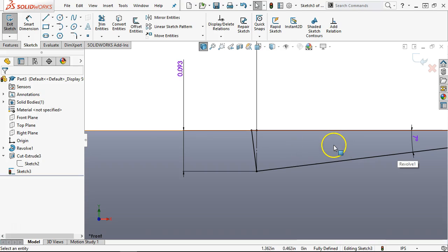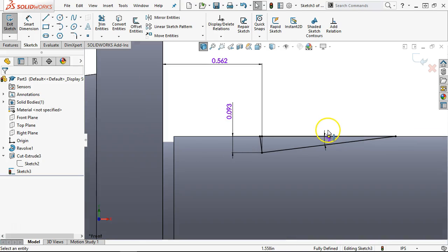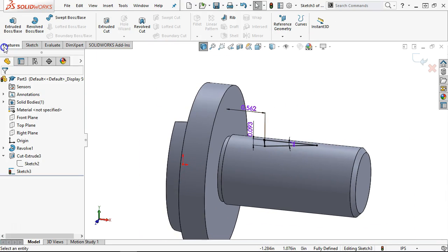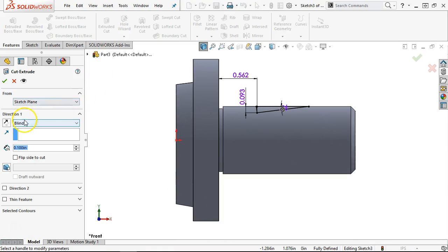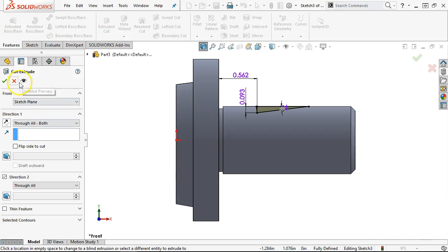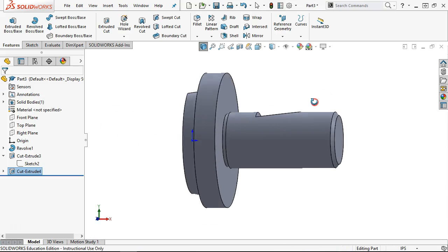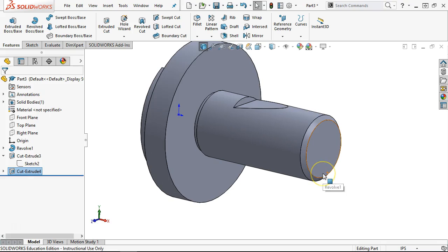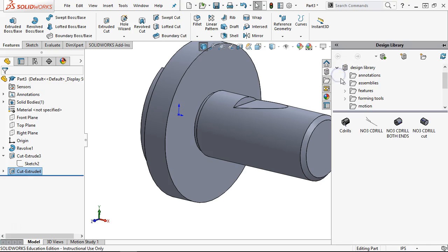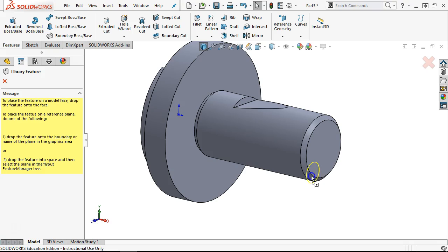Otherwise, this becomes a little bit more of an angle cutter and a little more complicated to make that edge vertical. And if it needs to be, we'll find out later, but I have the mechanism to go back and correct it by just converting those entities. Alright, so any radiuses? Okay, I do not see any radiuses, and then that leaves our design library geometry for the center drill.